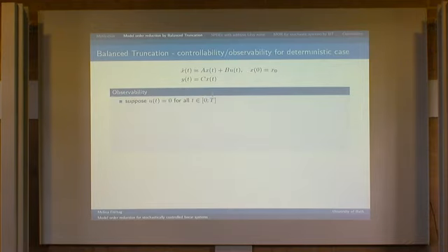Okay, so for that you need, this is where a little bit of control theory comes in. If you look at this equation up here, it's probably undergraduate mathematics: for u equals 0, so if you have no input, you can compute the solution to the system, and you can also compute the output. So y is just c times e to the fundamental solution, e to the tA times x naught. That would be the output if you had no input u.